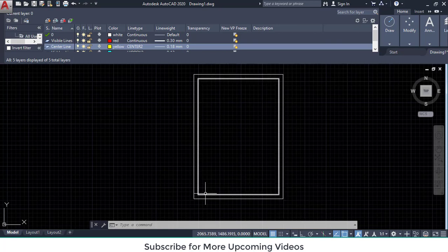And similarly, I can find the distance between front view and top view. Similarly, distance between top view and this margin line is 48.33 millimeter. The sheet division is available on my YouTube channel. So I type command line. This distance is 17.33.